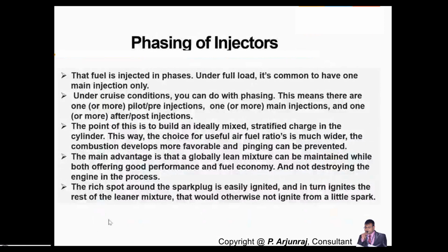The last important point with respect to phasing of injector is that it helps to identify the rich spot around the spark plug so it can be easily ignited. The rich spot here indicates high fuel and less air. It identifies that, and accordingly senses and moves towards the lean mixture, otherwise it will not ignite from the little spark.